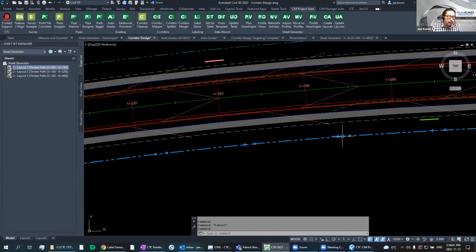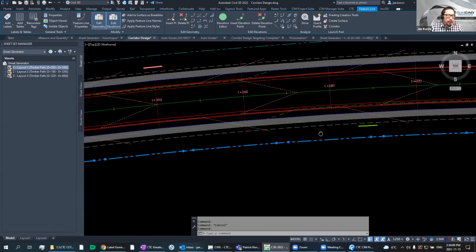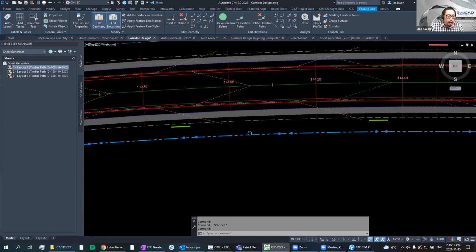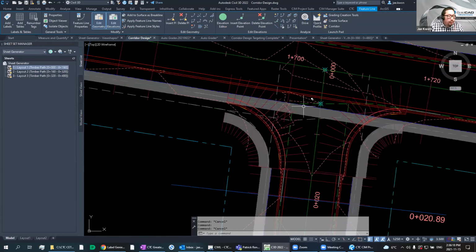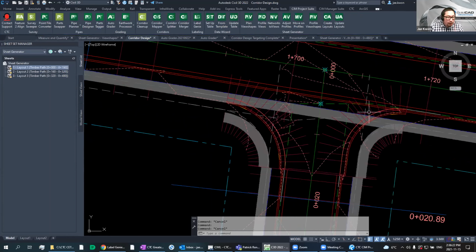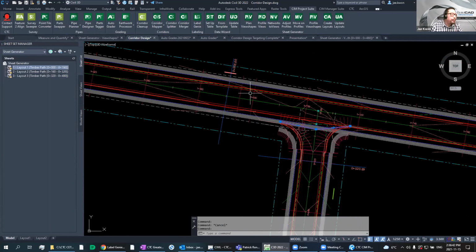We also have a right-of-way target that's going to be targeting what we're using as a base, basically a daylight line in the assembly. And there's also a little line representing where the intersection is, so that we can just use one region and then use a target mapping to cut out everything beyond the lane in this section going through. So a few things we got going on there. Let's just set those real quick.